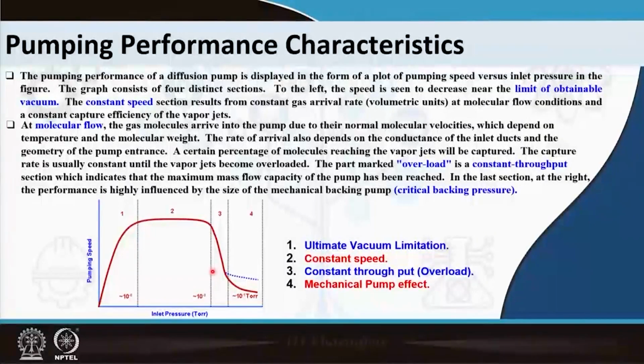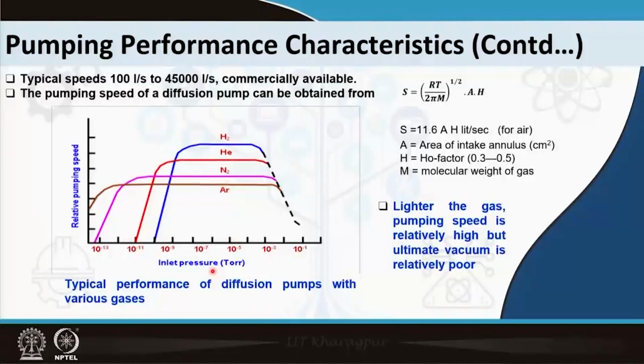At low pressures volumetric things are not conserved, but mass is always conserved. So, S1 P1 above the diffusion pump should be the same as S2 P2. Accordingly, you have to choose the matching rotary pumps. Okay. So, next slide, same pumping speeds.